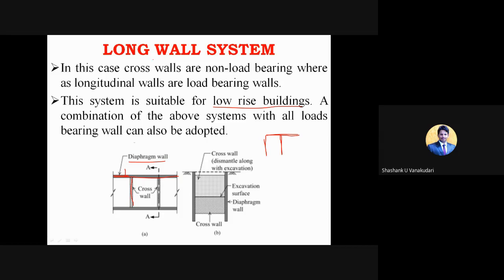And then the long wall system construction is very typical, with large block structurals and special pier blocks which come between the windows and carry certain loads from the lintel also, right? And then these horizontal sill blocks are not loaded, and in some designs the space between the piers is filled by a prefabricated unit consisting of an RC window frame with the complete window, which you can see in between the wall panel portions.